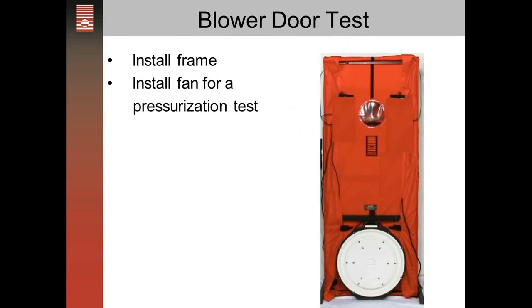Now you notice this is what you would typically see when you're setting up a blower door inside the house, but the enclosure is inside the house, so it is a little bit different, where this is really simulating setting up a blower door at the front door of a home, and that would be a method that might be used when you're testing an individual apartment unit or condo unit.